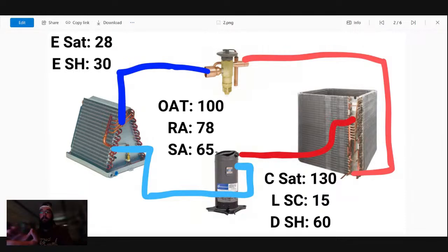I've had some of these cases where I've done this. I've loosened it off, that stem broke loose, it began actuating, and I ended up having to put it back where I started, because the issue wasn't a bad adjustment. The issue ended up being it was frozen internally, and I just happened to do it at a time where it was capable of coming loose. So that should be something we think about.